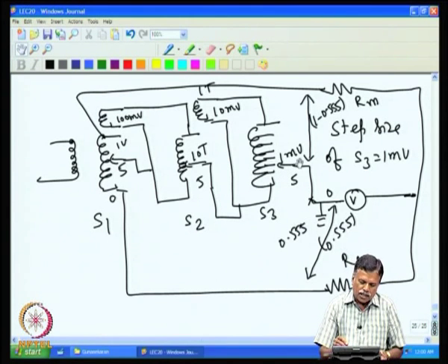The ratio of these two voltages is nothing but the contact points used in the ratio transformer. Since we are only worried about at what turns each one is, and there are integral numbers of turns, there is no question of any measurement error here, and the reading will be very accurate.